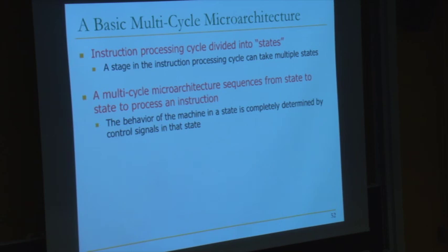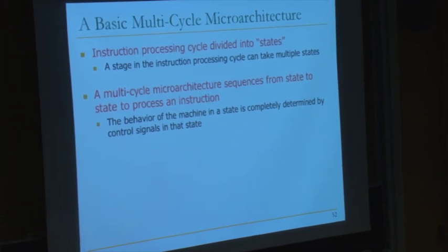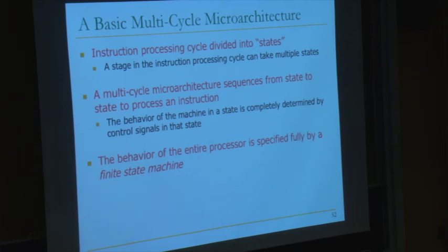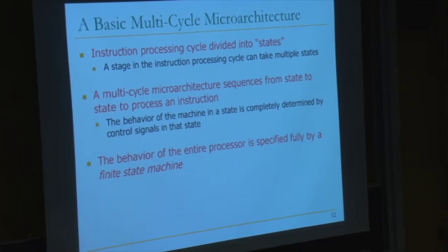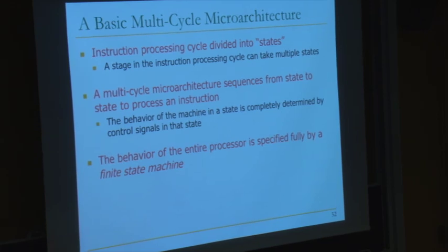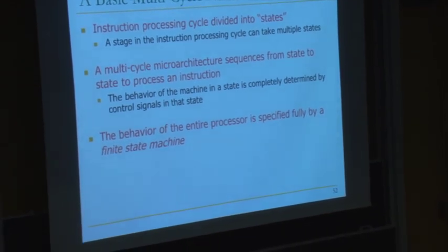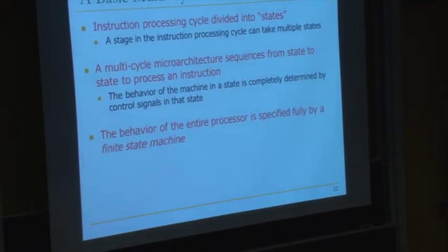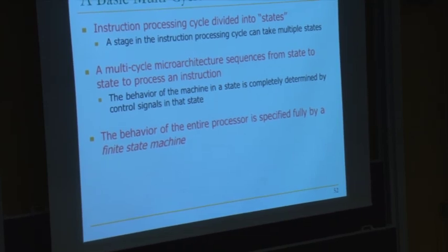And the behavior of the machine is completely determined by the control signals in that state. And we will see what those control signals are. And the behavior of the entire machine is fully specified by this finite state machine. You could actually do this if you want to design a microcoded x86. You could have a single state machine that implements all of the x86 instructions.